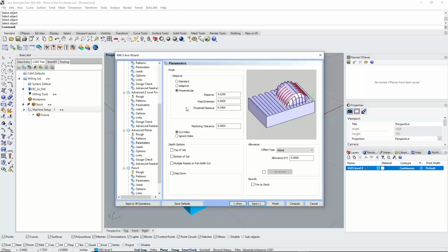So this one is actually going to ignore, in our case, any cuts that are going to come out with a bad finish along the x-axis direction. And it's going to cut everything along the y, and then it's going to switch directions and cut along the x. So you end up with kind of a tool path that does a really good job in both directions. But we'll go with just the standard cut. We shouldn't need anything fancy because we're going to use angle ranges.